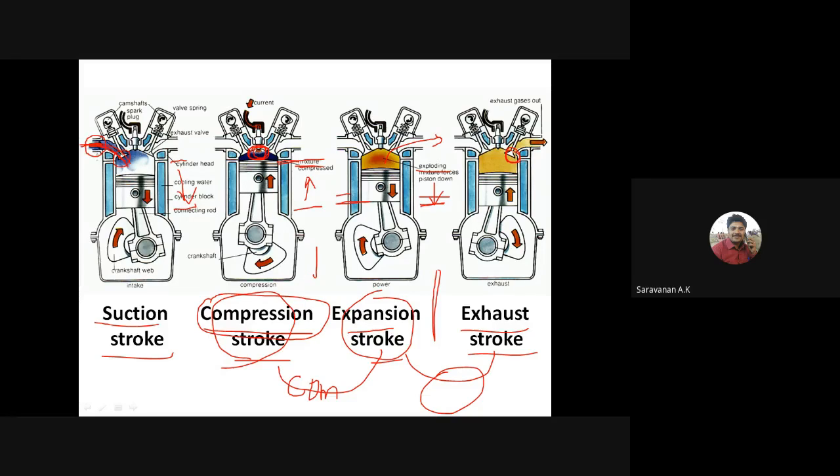Then the pressure and temperature inside the cylinder are still high relative to the surroundings, right? And the pressure differential is created through the exhaust system, which is open to the atmospheric pressure. This pressure differential causes much of the hot exhaust gases to be pushed out of the cylinder through the exhaust system when the piston is nearer to the BDC condition, right?